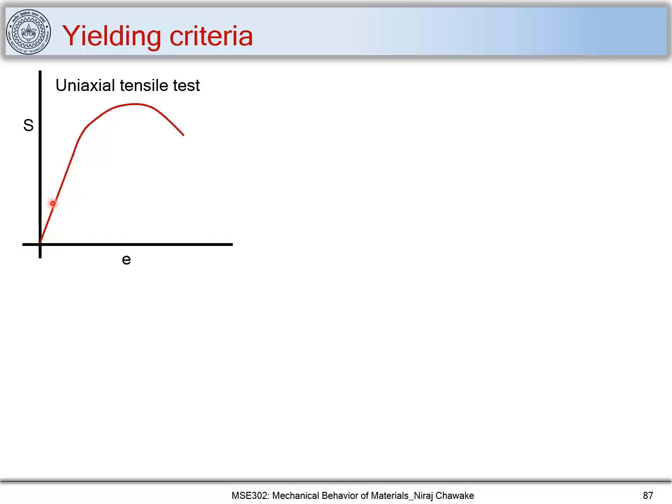The first portion shows a linear region, where the material behaves in an elastic manner. The non-linear region is where material demonstrates a shape change, or a permanent deformation. The transition from elastic to plastic region, we figured out using the yield stress. So when I deform material above yield stress, it undergoes a permanent shape change.